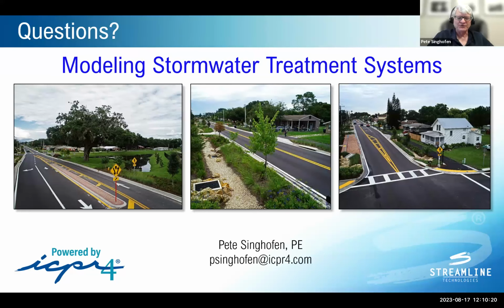But it was in the rainy season and everything was dry except for the pond at the downstream-most end that had a little bit of water in the bottom, which our simulations indicated should happen. The water table's a little bit higher down there. So yeah, these are designed really well. And I did not see any sediment accumulation in the rain gardens, anything that was obvious. There might have been some in the rock, but it looked pretty good to me.